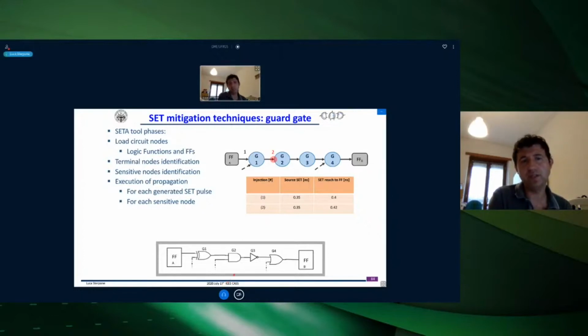The question is, also if you have double redundancy, you can always have the possibility of having 2 out of 3 circuits being affected by radiation. And you wouldn't know which one of them is the correct one, because if 1 circuit is wrong and you have 2 circuits working, you don't know which one is correct at the end. The question is, would it be better to have triple redundancy or better to have a shielding solution of the circuit?